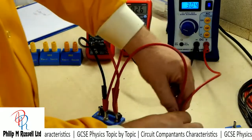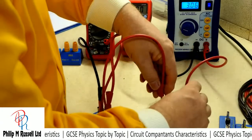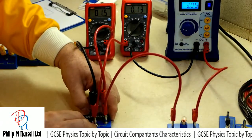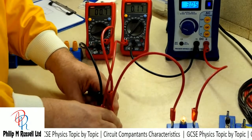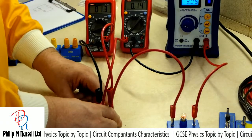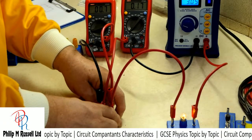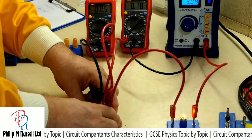Better way of trying to see this would be to put the bulb in the circuit with this. So let's now have the bulb. I've got no switch in here, but I can change the resistance, and as I change the resistance, so the bulb will change its brightness. So here I've got maximum resistance, and as I remove more and more coils from the resistor, then the bulb becomes brighter.